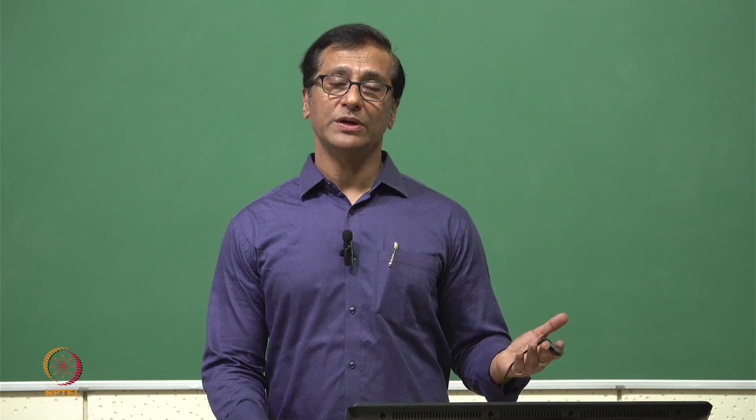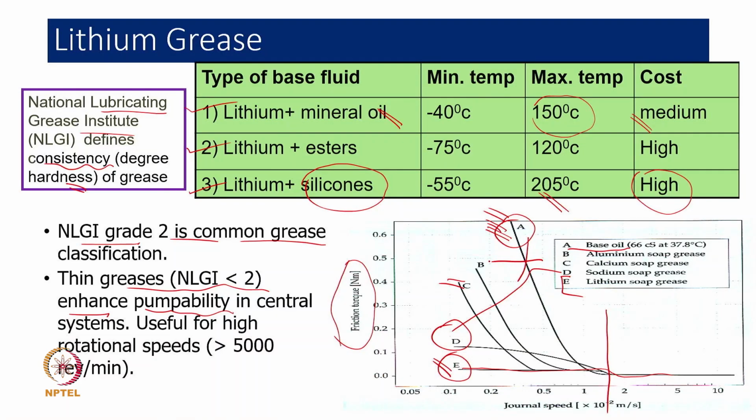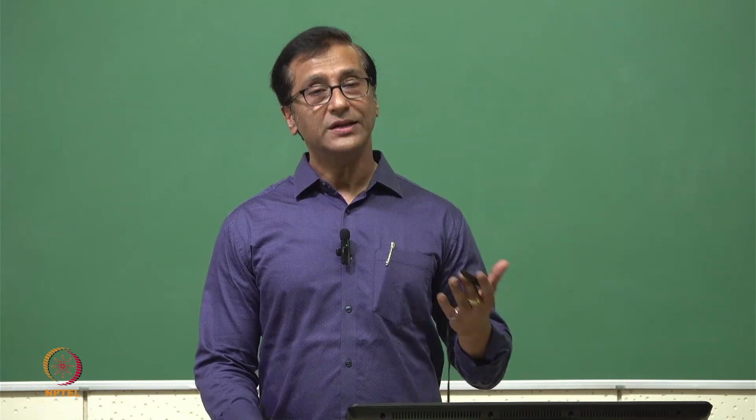Otherwise, the motor will not be able to rotate the shaft. So that's why this can will cancel, and I'll prefer to go with this kind of grease. Assuming directly the liquid lubricant will always be preferable, because it is less viscous, is not necessary. We need to really justify it in an appropriate manner.